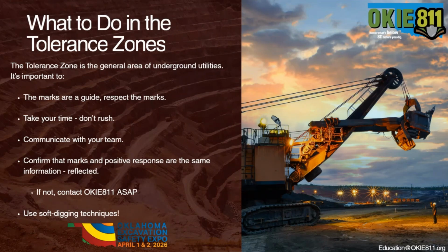When working in the tolerance zone, it is very important to take your time and not to rush. It's easy to make mistakes when we hurry a project and when we push things too fast. So it is important to take your time within that area. It's a great practice to communicate all of that with a team. Have a toolbox talk before excavating and let them know about the tolerance zone and what to look for. What is in that area? Are there obstacles in the area? Is there debris in the area? Is weather affecting where those marks are and if you can see them?